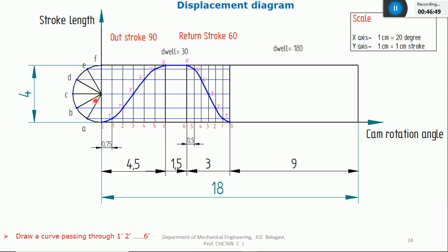Using the protractor, keep the center of the protractor at this point, and take this vertical line as a reference line. The protractor has to be towards your left side, similar to this semicircle. At the first 30 degree, indicate point E, D, C, B, A. Or you can start from here also. For all examples, we have to take 30 degree only, because you are dividing into 6 equal parts. The total angle is 180, and 180 by 6 is 30.